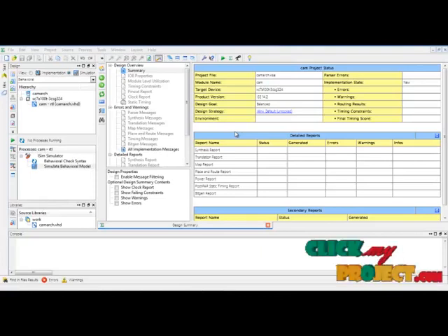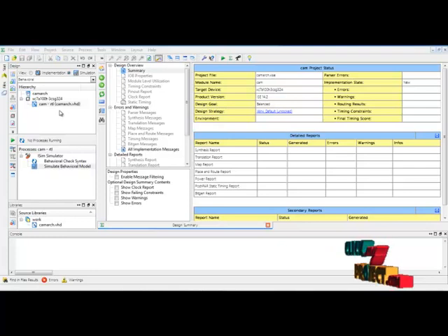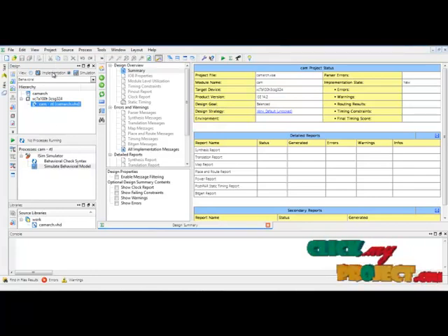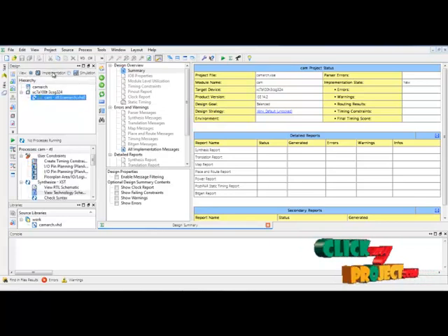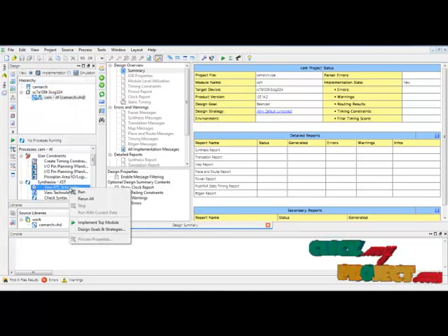Now I am going to explain the running procedure of our project. First, open the cam.vhd file. After that, I first use the RTL schematic by selecting the implementation radio button and then run view RTL schematic by right-clicking it and clicking the run option.